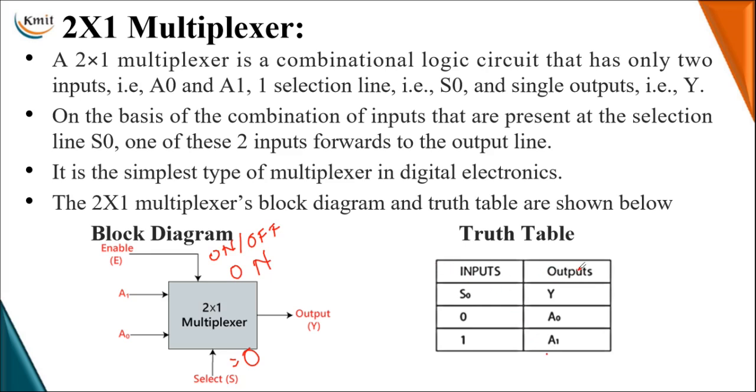We write that in the truth table, with the selection inputs taken as inputs and only one single output. Based on the selection inputs, which input is transferred to the output? These inputs are also in binary form, so the values might be 0 or they might be 1.